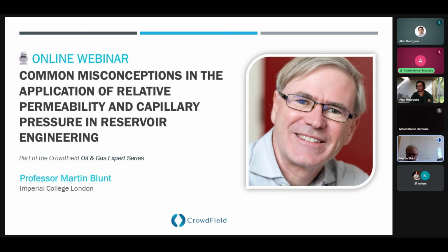You can't, Alan. The reality is, what you can do is use a repeat formation tester. Imagine I measure pressure as a function of height. I can measure pressure in the water here, and I can measure pressure in the oil here, and I look at the pressure difference between them. So if this is pressure and this is height, oil does this. Water, you see at a lower height, and it does sort of this. And what you do is you extrapolate the two. You're extrapolating to the height at which theoretically you would see the two the same, and you call that the free water level.